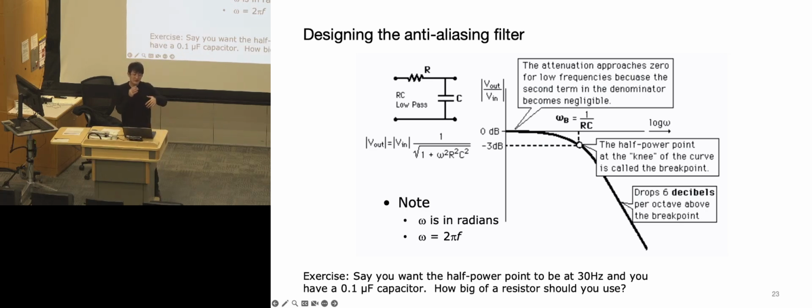So it's still good to have some additional protection in the hardware or in the software, to make sure you are sampling at the right frequency, rather than purely relying on the ADC's hardware circuits to do the job.